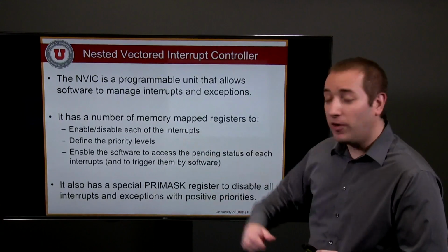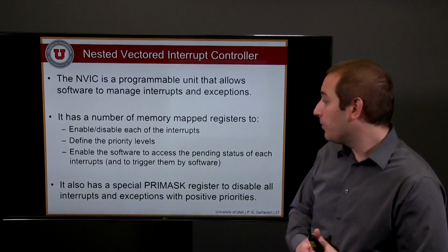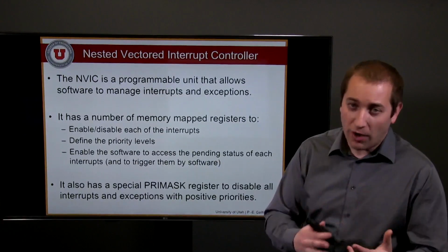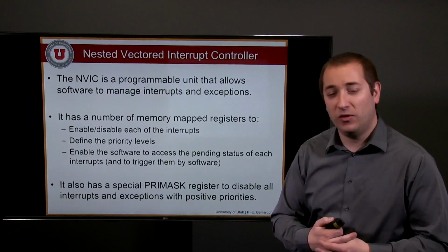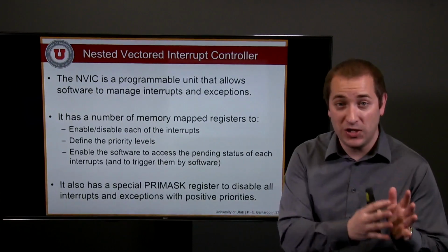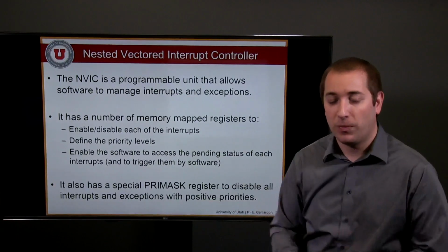You'll also be able to define the programmable priority levels, and you will also enable the software to access the pending status of each interrupt. So when you receive multiple interrupts, you'll be able to see which one has been triggered.